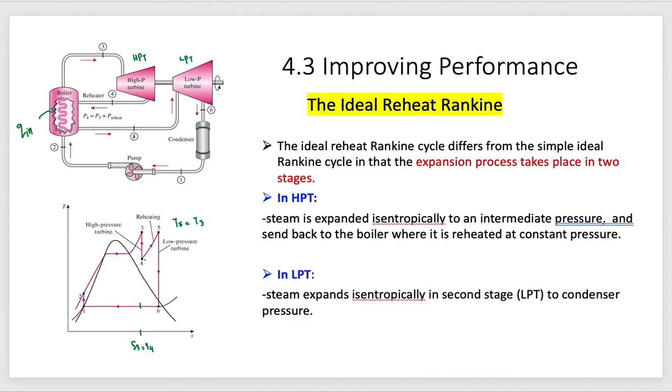Okay, so the steam will enter at state 5 at the entrance of the LPT. Again in this LPT there will be isentropic expansion as S5 is equal to S6. And what happens is the pressure will reduce to state 6, as well as the temperature.